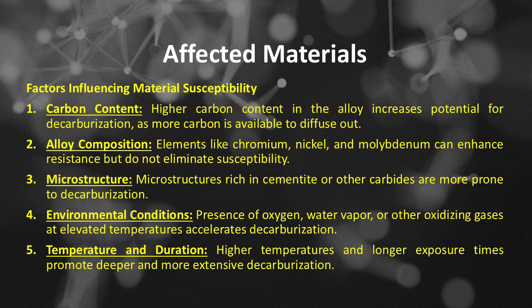Number 4, environmental conditions, presence of oxygen, water vapor, or other oxidizing gases at elevated temperatures accelerates decarburization. And number 5, temperature and duration. Higher temperatures and longer exposure times promote deeper and more extensive decarburization.